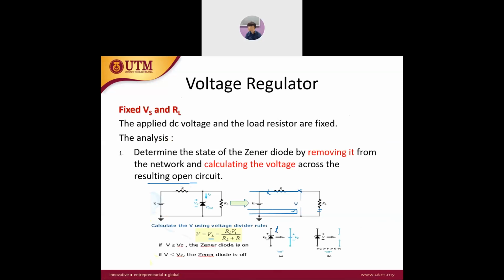The diode is turned on when it operates at Vz, much greater than the knee voltage, in the reverse bias region, since it's designed for breakdown regions, with opposite polarity. Next, it is off where the value of voltage is between Vz and 0 volts, the diode is turned off.